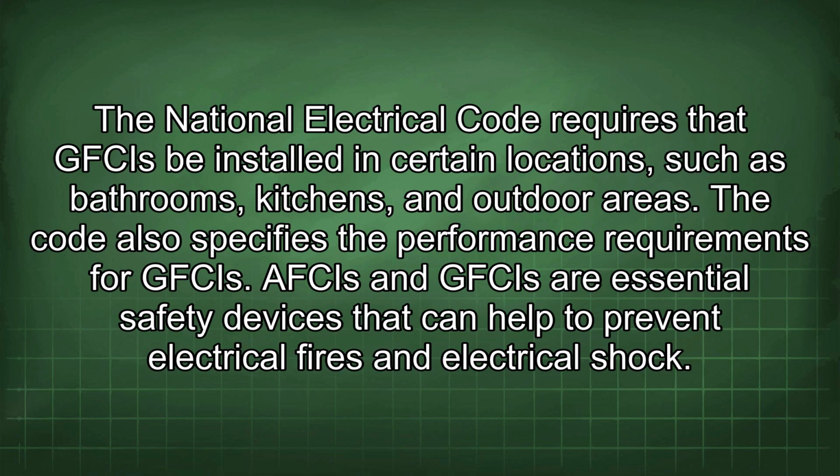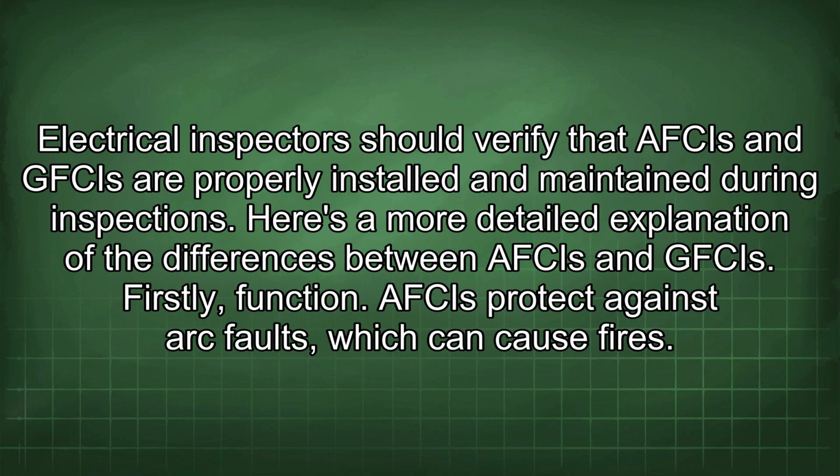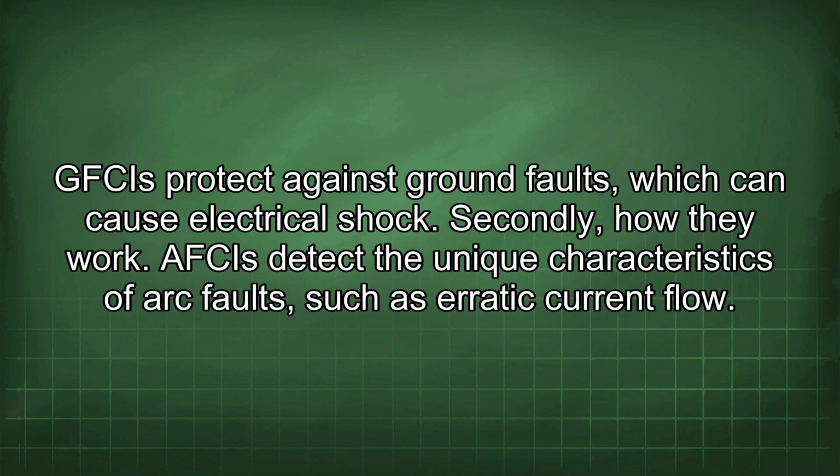AFCIs and GFCIs are essential safety devices that can help to prevent electrical fires and electrical shock. Electrical inspectors should verify that AFCIs and GFCIs are properly installed and maintained during inspections. Here's a more detailed explanation of the differences between AFCIs and GFCIs. Firstly, function. AFCIs protect against arc faults, which can cause fires. GFCIs protect against ground faults, which can cause electrical shock.